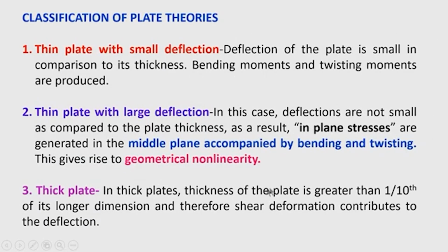Okay. Now, first let us discuss what are the different theories based on which we will proceed to formulate the problems on plate. Three theories are developed for studying the plate. First theory is a thin plate with small deflection. Second theory is thin plate with large deflection, and third theory is a thick plate theory.